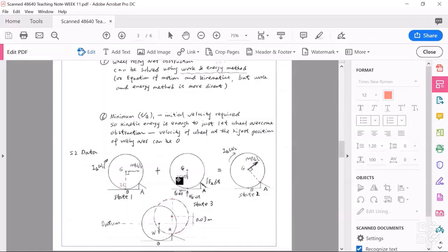the impulse generated by the weight force of this wheel, by reaction force Mb, by friction force Fb, and by the impact force Fa. Fa should be a variable, so to express its impulse, we use the integral of Fa with respect to time.